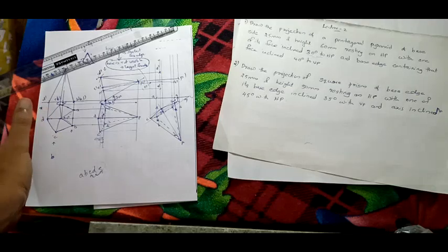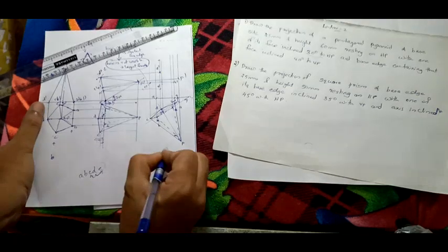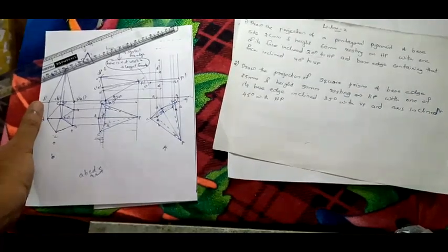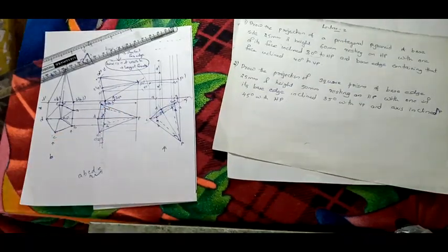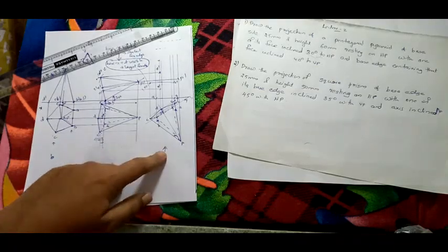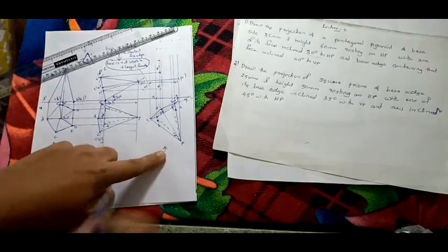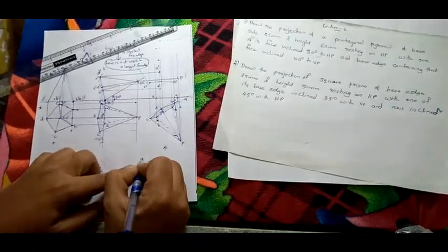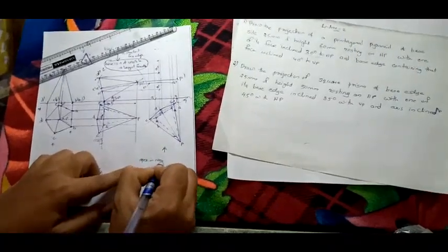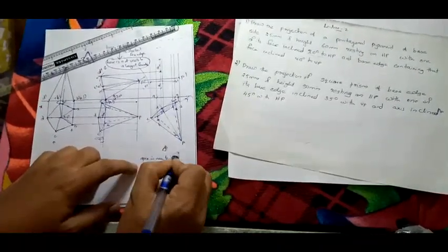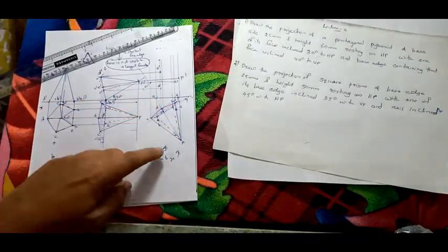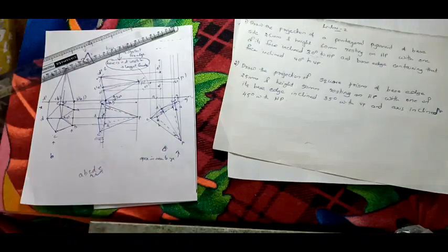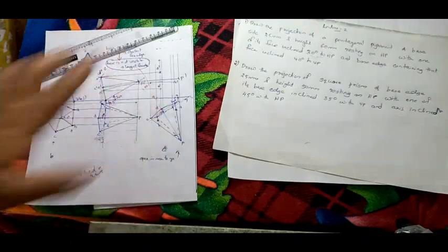Now visibility. Here also, if we are looking from here, this type of view you will not be able to say whether the base is visible or not, right? So I will tell you an important hint. If the apex is nearer to you, that is, if you are viewing from here, if P is nearer than A, B, C, D, E, then the apex is visible, base will not be visible. If the apex is visible, the base is invisible.